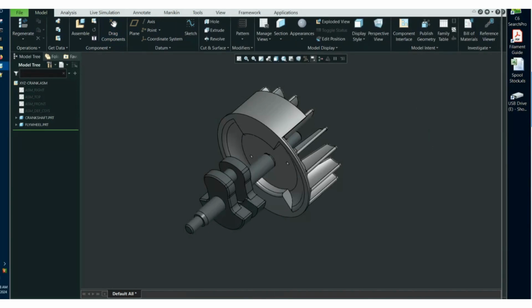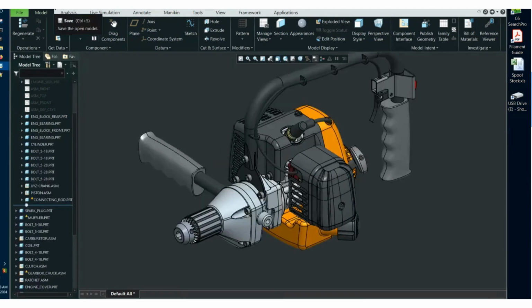Whoops. We regen the assembly. Now we have the new name. It's in session. Now I can save this assembly, and any objects that are also referring to XYZ crank are not broken. Everybody's happy. All of the objects, in case in point, will be recoverable. Not only this assembly, but something else that might now be looking for XYZ crank instead of looking for, excuse me, crank assembly by itself. So that's a little bit of how we go about dealing with the renaming of stuff when we want to transfer something over to a new name.